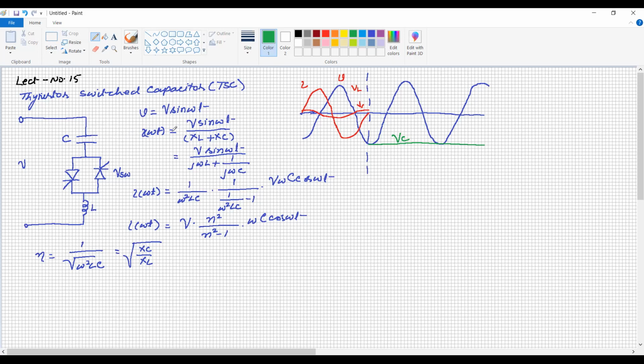So when there is an inductor, it is going to absorb the reactive power, and when there is a capacitor, it is going to generate the reactive power, or supply the reactive power to the transmission line. Now, the voltage across the capacitor also plays a role. For example, if you take some waveform to understand